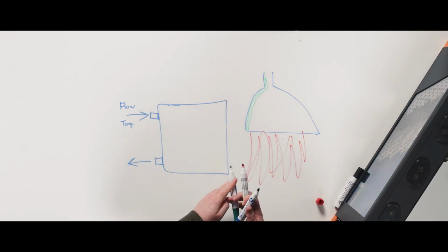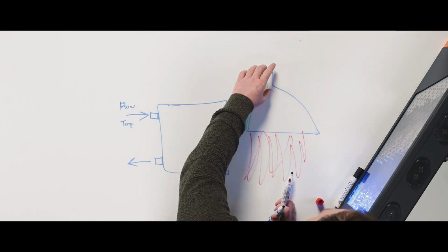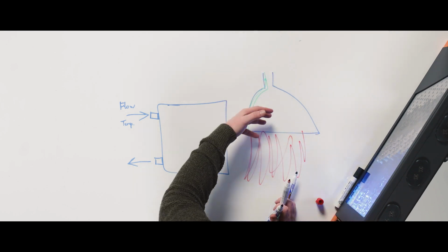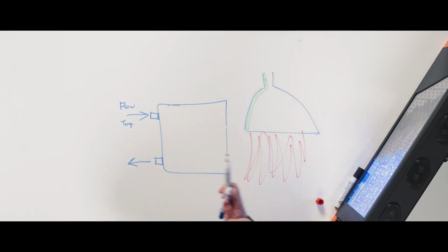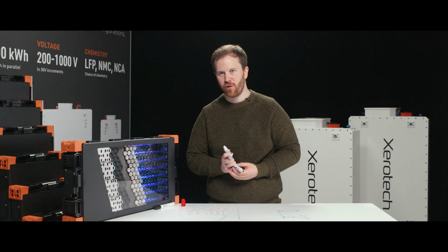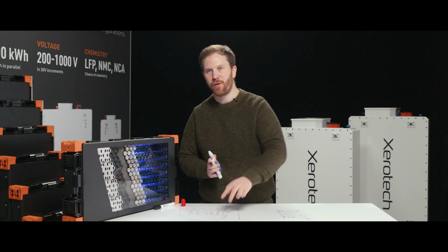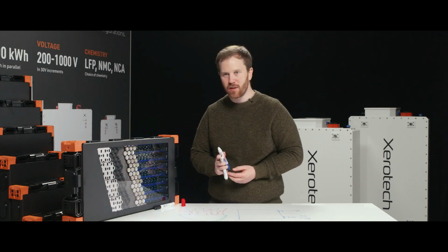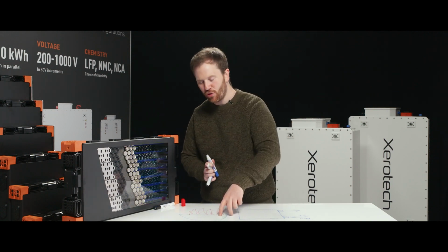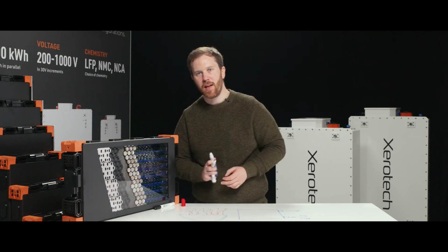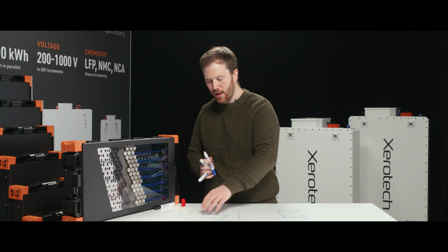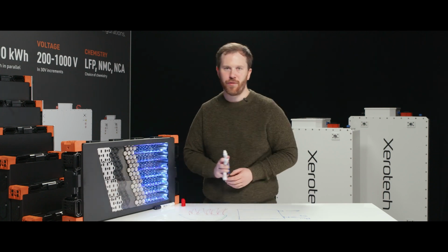So this does two things. It cools the rocket engine wall and recovers energy and increases the efficiency of the system. But this would be an example of incredibly high pressure drop systems. You need massive cooling pumps to do this. Thousands of horsepower of cooling things to drive that rocket fuel through those nozzles. But it results in extremely high heat transfer to deal with this. But the temperature gradients are also going to be very high.